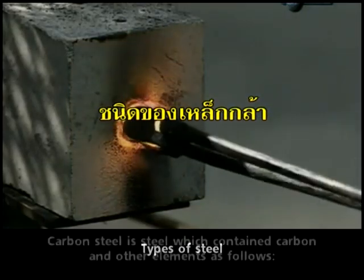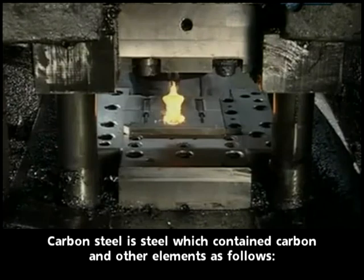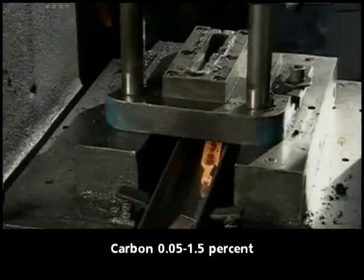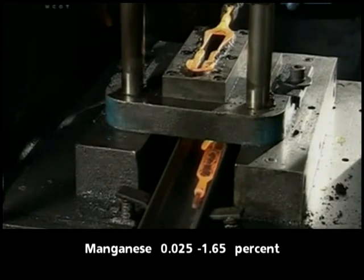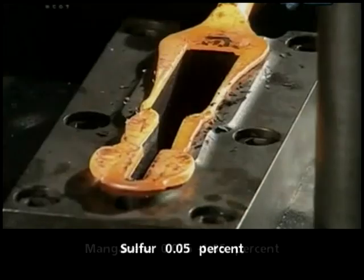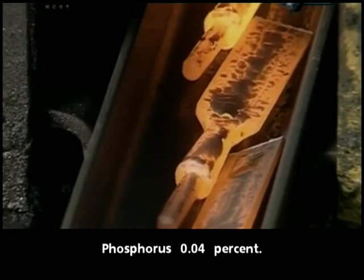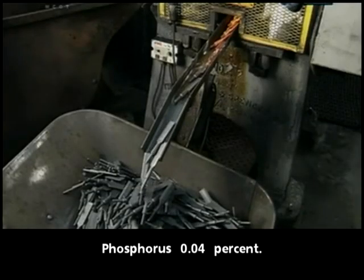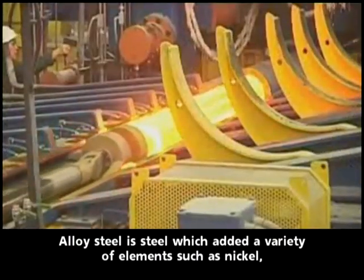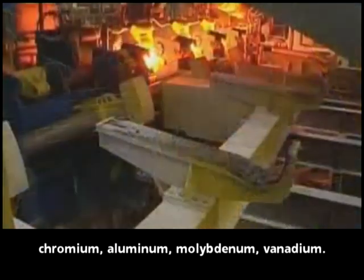Types of steel. Carbon steel is steel which contains carbon and other elements as follows. Steel 97%. Carbon 0.05 to 1.5%. Manganese 0.025 to 1.65%. Sulfur 0.05%. Phosphorus 0.04%. Alloy steel. Alloy steel is steel to which a variety of elements are added, such as nickel, chromium, aluminum, molybdenum and vanadium.